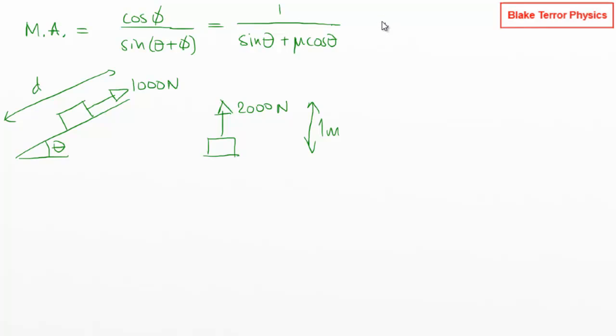So the engineer in us is saying, we've got this target mechanical advantage. Target mechanical advantage is 2. We know that's what we need to be able to achieve. So what is the maximum mechanical advantage we can get in a particular setup with friction? Because the friction is limiting what we can do for mechanical advantage.